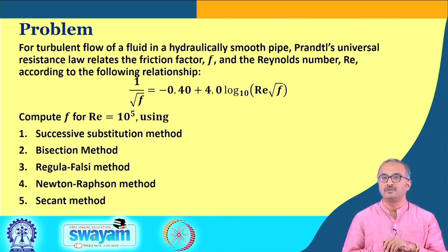The second use of the knowledge of friction factor is that sometimes we need to find the rate of heat transfer or mass transfer in terms of the heat transfer coefficient or mass transfer coefficient. Many times these two coefficients are not available directly. In that case, we can find the values of the heat transfer coefficient and mass transfer coefficient from the value of the friction factor using something called analogies. These analogies are taught separately in courses on transport phenomena. So, in many ways the knowledge of the friction factor is often needed to solve engineering and scientific problems.